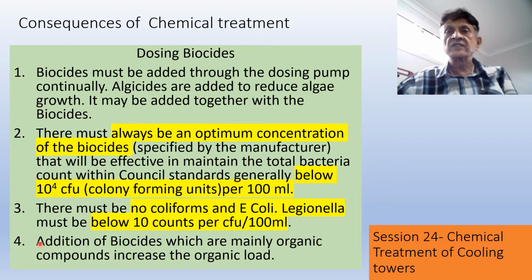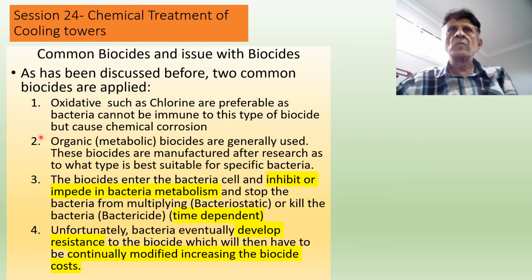Additional biocides, which are mainly organic compounds, will increase the organic load. The common biocides that are used are oxidative ones and chlorine, which are preferable, as bacteria cannot become immune to this type of biocide, but they will cause chemical corrosion.